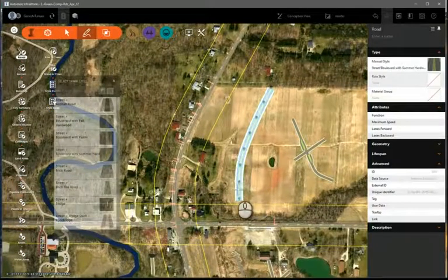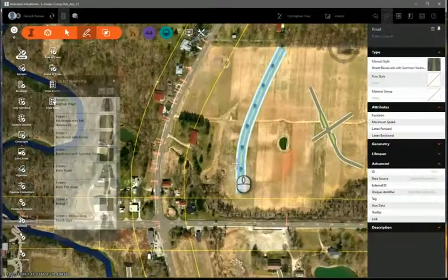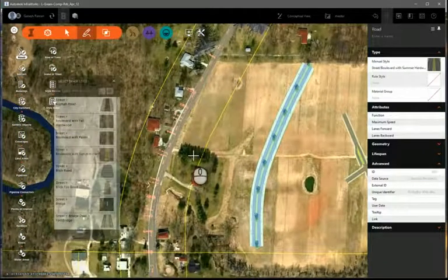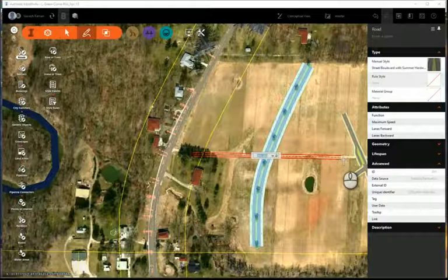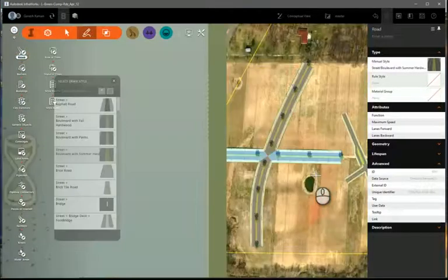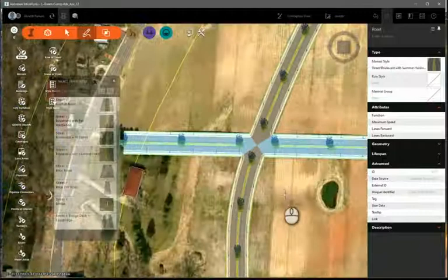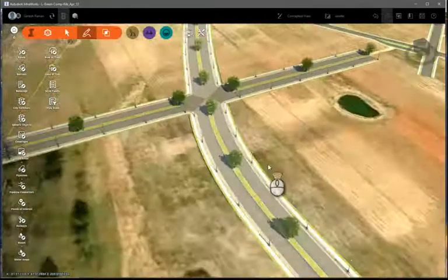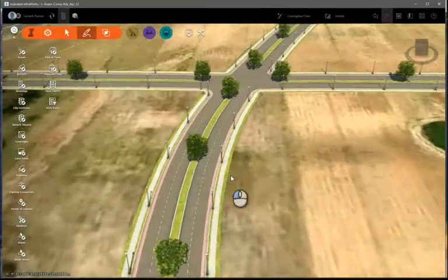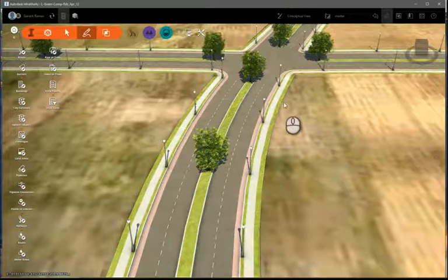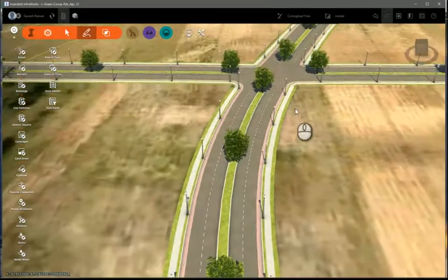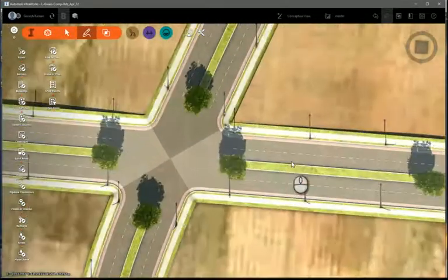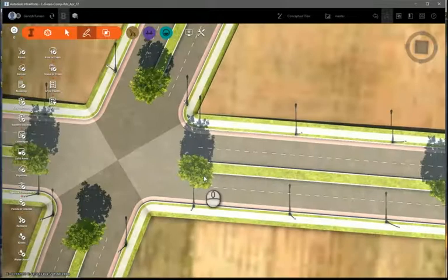I have that curvature, and now I'm going to create a crossroad that matches Royalton. So I'm going to cross over this over here, and there it is. Now I have a default roadway that is directly from the style menu. As you can see, it has trees and all those things. These can be changed, removed, added. All those things are done through the city furniture option. We are interested now in creating a dedicated left turn lane from the median here.